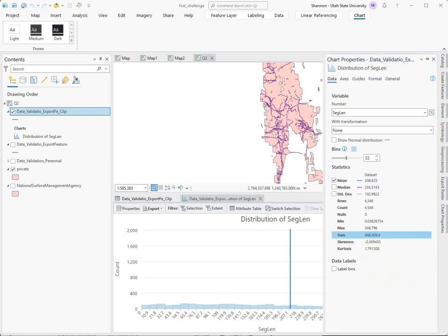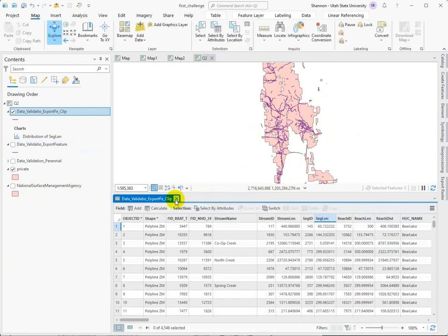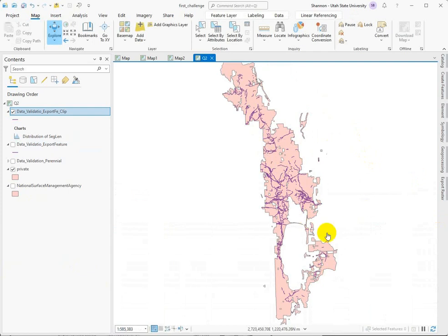How else could you approach this? You could run the intersect on it. You could, like I said about select by location, I don't know that I would trust that in this case. You know, it doesn't really matter what order you go after the two individual pieces in. So yeah, I didn't really see a lot of alternative approaches to this one. The key is knowing that you have to update those lengths because they don't automatically update.